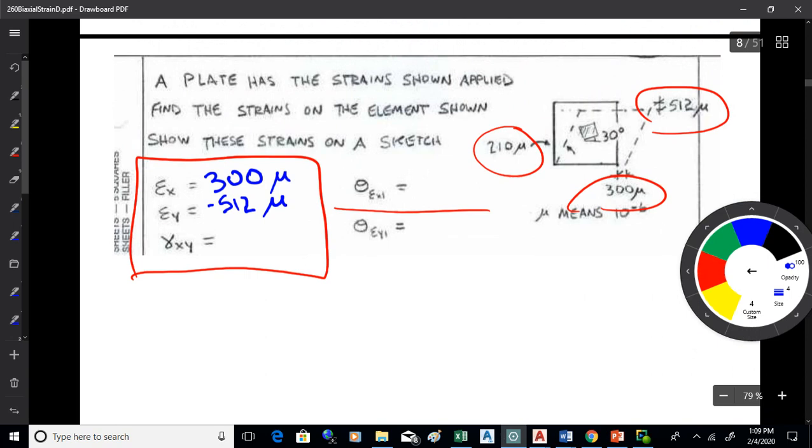And the shear strain is shown all on one side, which may not be an entirely realistic way to show it. These are more schematic kind of sketches that you can dimension. They're also quite exaggerated in the amount of deformation. So there's the shear strain. And that isn't shown entirely on one side. Really, in reality, it would be on both sides of the angle, as I was just showing you a minute ago. But just for ease of dimensioning, it's shown as though it's all on one side.